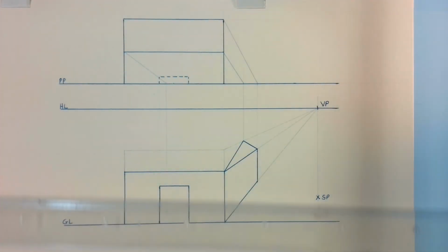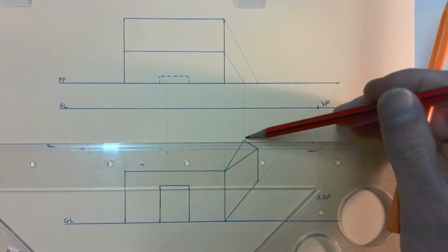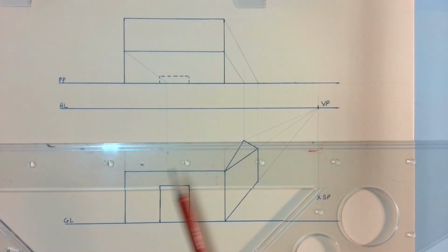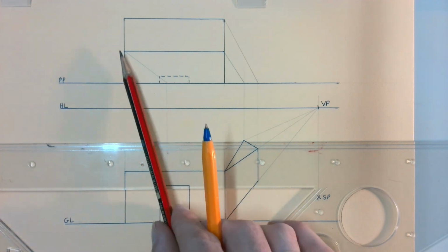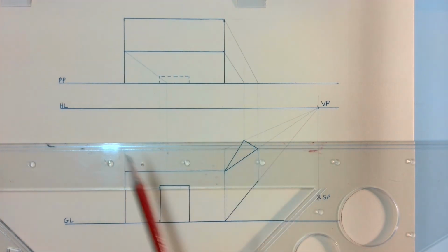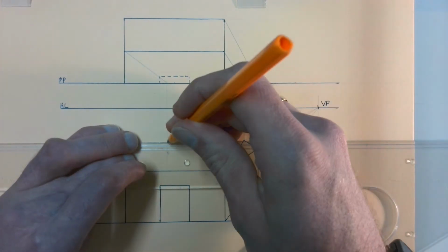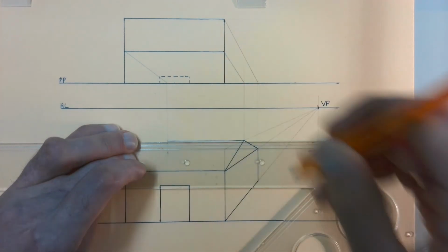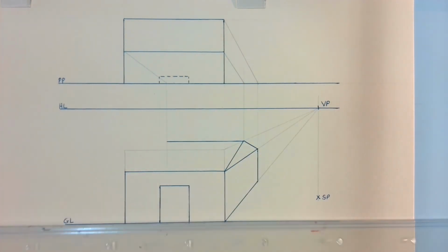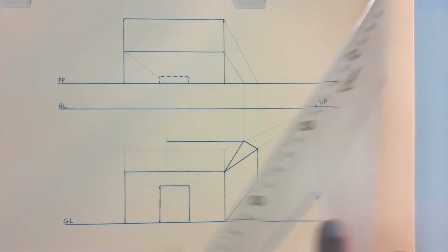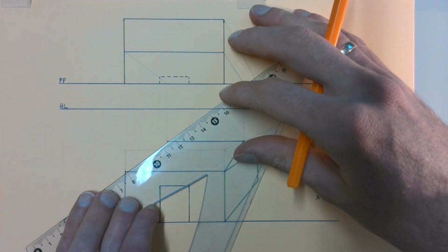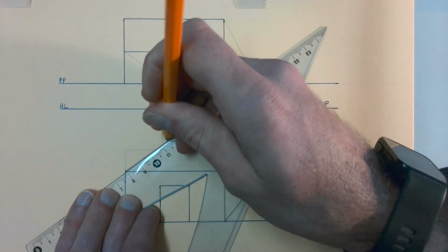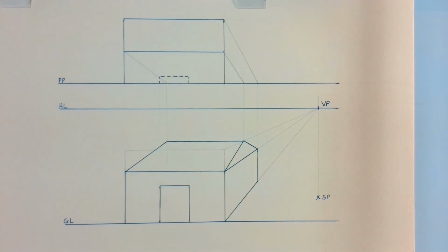Okay, and then we're going to project this point straight across, because remember, in a 1-point perspective drawing, any line which is horizontal is going to stay horizontal in the 1-point perspective. So this line's horizontal there, it will remain horizontal here. So we can simply take that line all the way to that point, and we know it's going to be a dark line because that's the top line of our roof. And then the last line for that roof to draw is going to be joining that roof, of course, to the point on the top of the wall over there. And that then completes our roof.